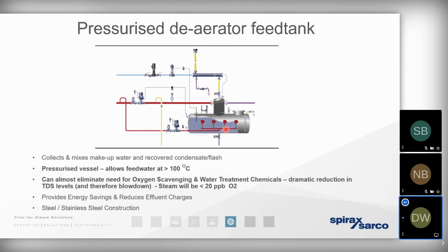And because we're generating steam from pressurized hot water, the pressure has actually purged off a significantly greater amount of the air and the other non-condensable gases. So we've got less corrosion. It means we need to add fewer chemicals to the hot well to polish off that last remaining mass of air. So it means we're not actually changing the water chemistry fundamentally, which means we need to perform less blowdown. And that in turn means we get drier steam being produced on top of the energy cost saving there.